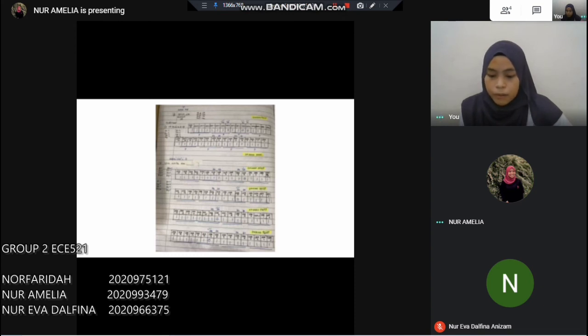LED1 on, we have the value of 0x0000FFEF, while LED2 on, we have the value 0x0000FFDF. LED3 on, we have the value 0x0000FEFF. And while D4 is on, we have the value of 0x0000FDFF. And next, we will proceed with the coding.